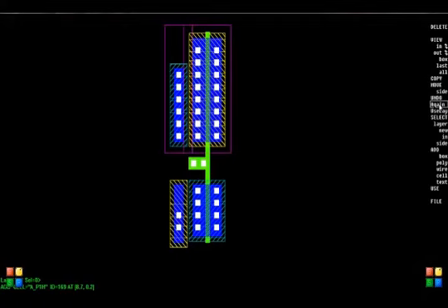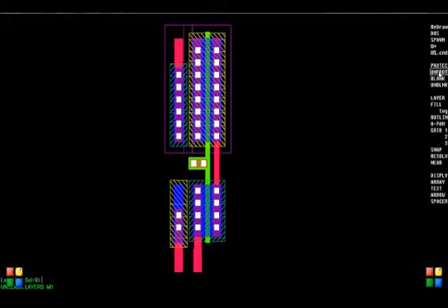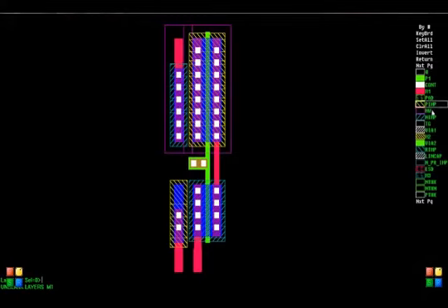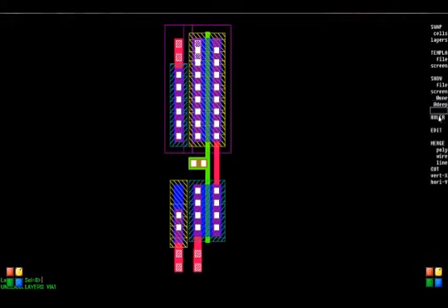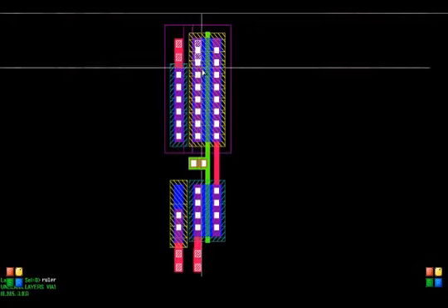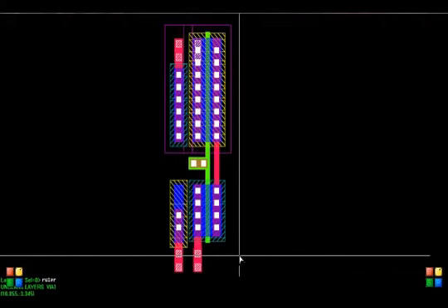So let's unblank the metal masking layer. And the metal layer is shown in red. And so all the contacts connect the silicon below to the metal above. Now in this process I have another layer of metal, and that is called second metal, and it connects to this red metal one by another masking layer that's called a via. So the via provides the connection between the metal 1 and the metal 2. So let's unblank the via layer, VIA1, return. So you can see that there's via layer here, some here, there's some vias here, some vias here. So they're going to connect to the second metal.